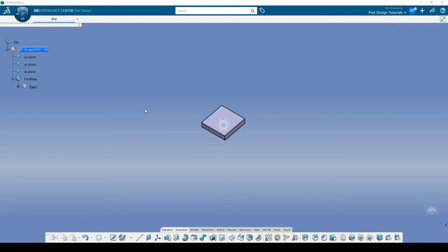So then let's rewind everything and get back to just the sketch so I can talk about that again. But before I do that, I wanted to show you, I could just Control Z and undo and get back to before we padded this thing up. But what you can also do is you come over here and hit the plus sign. You see that there's a pad, and then the sketch is underneath. The sketch is the parent of the pad, and it gets absorbed underneath.